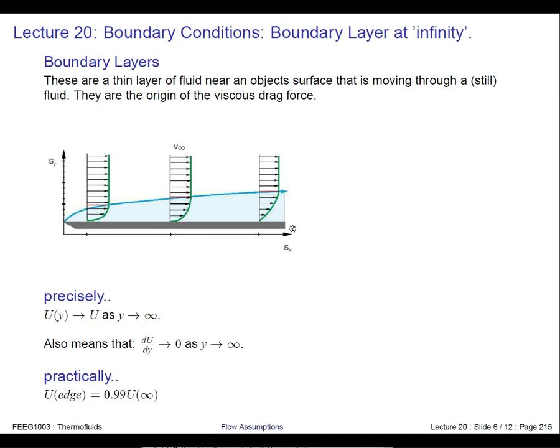Okay, so the velocity of the wall is 0 at the wall, and far away from the wall, the flow doesn't know about the boundary, so it's still moving at its free stream velocity. And so the boundary layer is this region that connects the 0 velocity at the wall to the free stream. And this change in velocity with space down the boundary is called the boundary layer.